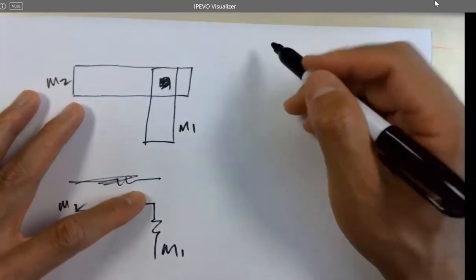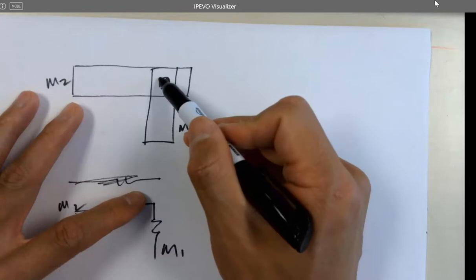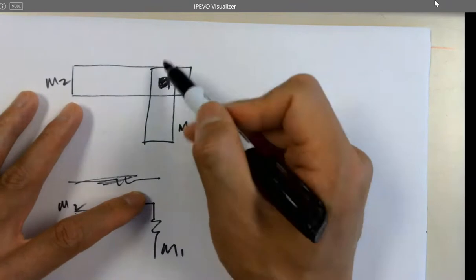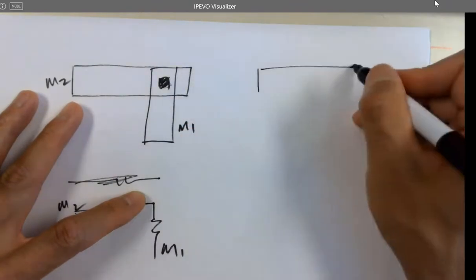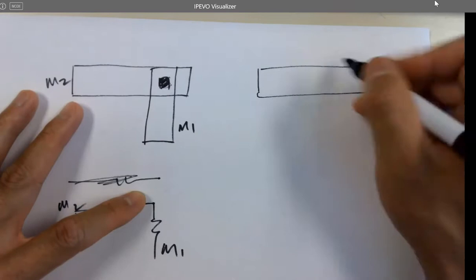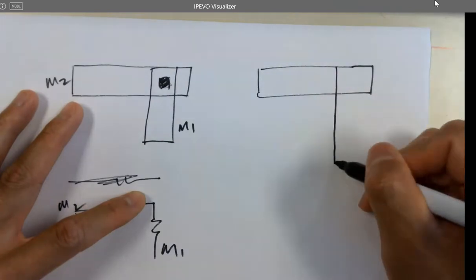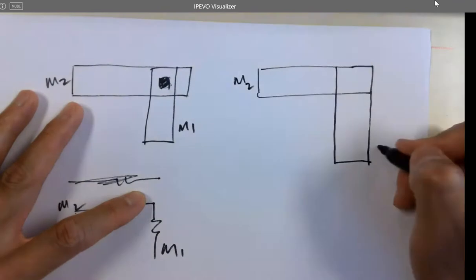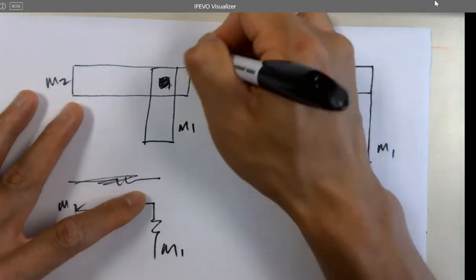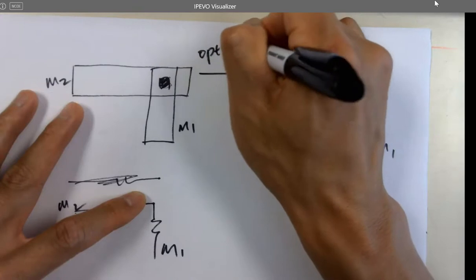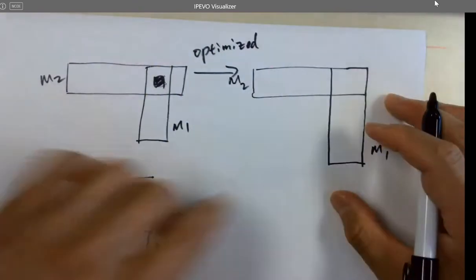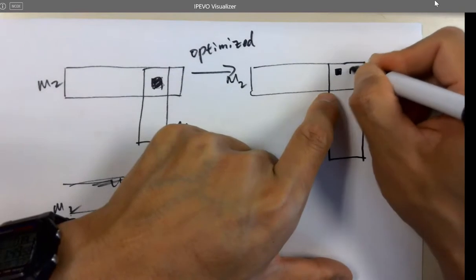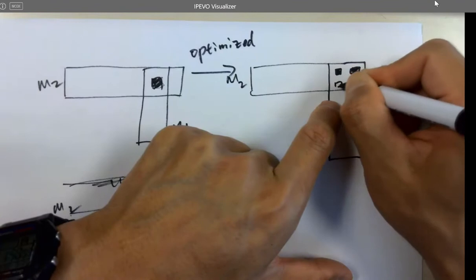A lot of times, you do not just use one via. Instead of using one big via, you use multiple smaller ones. It looks like this. I'll just draw it line to this edge. I want to show this because you are going to see that in the future during the layout. So instead of making one big via, there are a couple of different smaller vias.